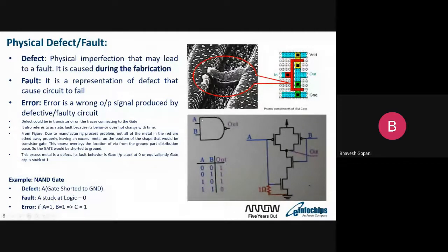we are trying to identify the reason behind this, because this flop has many downstream logic. This is not only one NAND gate, there are many other combo logic. So we need to identify whether this is the suspected gate where the failures are, and also not based on only one chip, there are n number of chips that need to be tested.